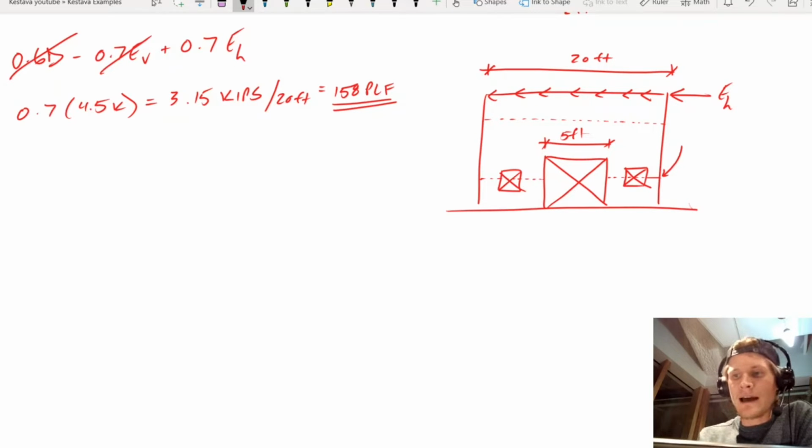So even though you have up above here, you have full shear wall, really, everything good. In terms of shear, it's got to travel all the way down that wall down to the foundation. So right there, just for shear capacity only, you would be screwed along those windows and doors. So you'd have to really check that out. And that actually dives in, I'm getting off the rails here. That actually dives into what's called perforated shear wall design.